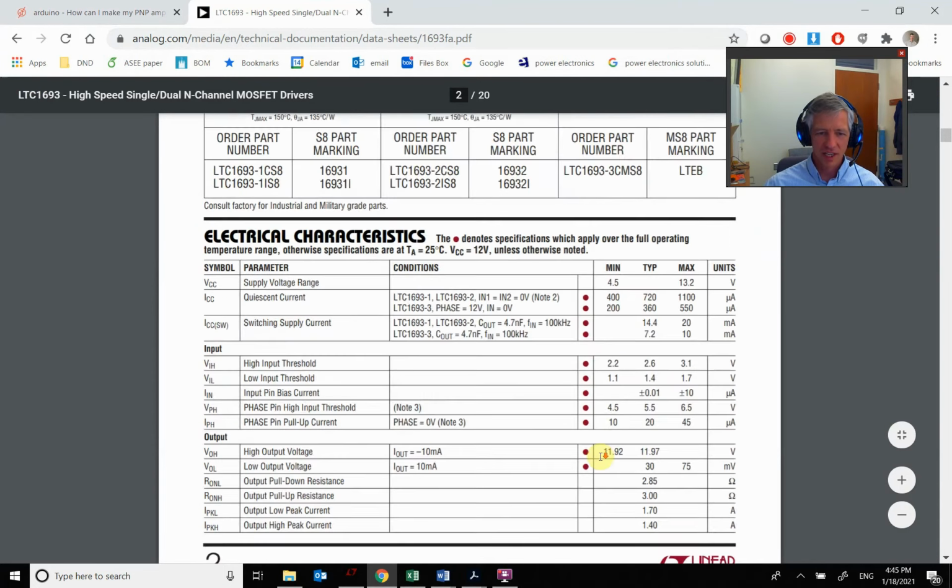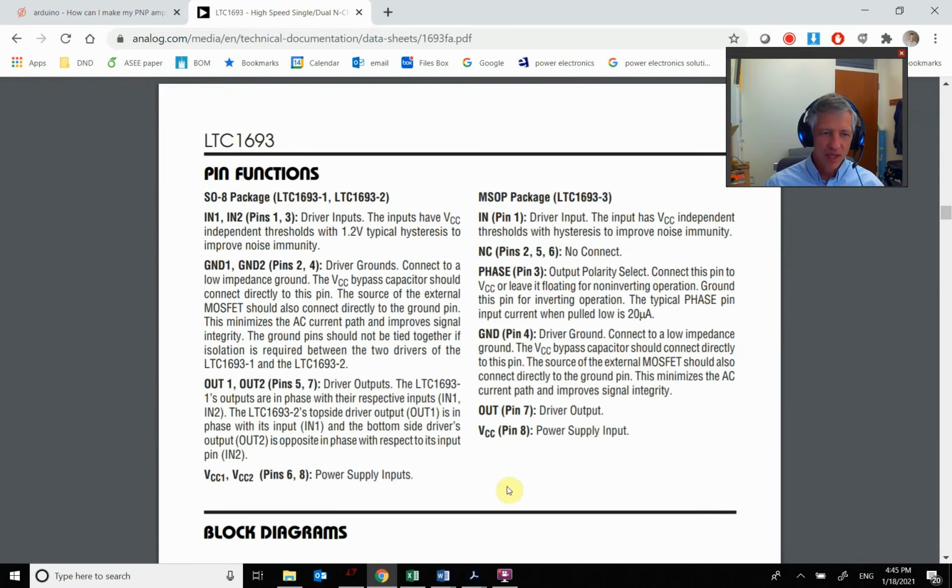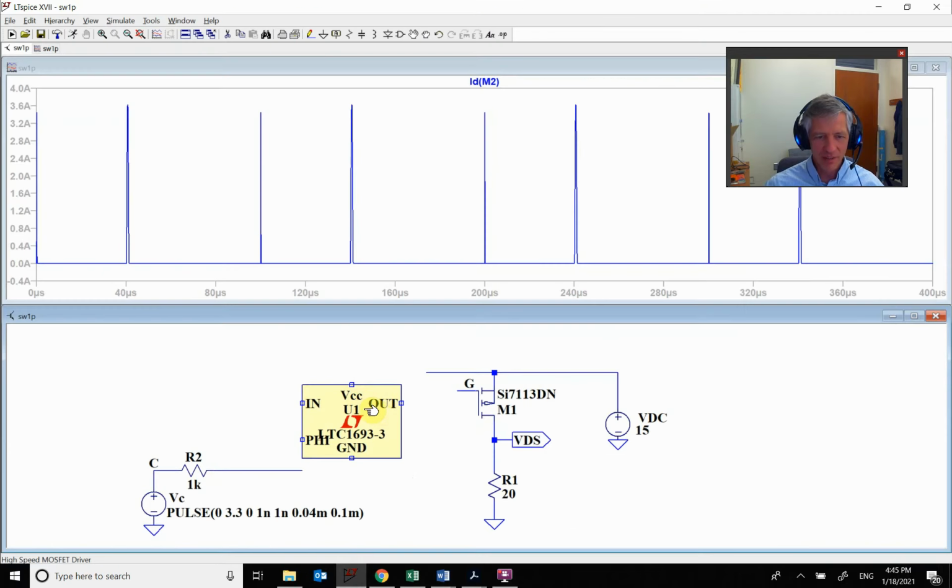So we've got these big long circuits. Let's find out what the pin structures are. Okay, here are the pins, okay? So we have output pins, grounds, input pins, okay? So if I come back over to LTspice, VCC, oh, well, that's my power. So I'm just going to tie this up to here. I have the ground, so I'm just going to tie this point to ground. I have the input. So this becomes my input, and then I'm going to tie this point to my output, okay?